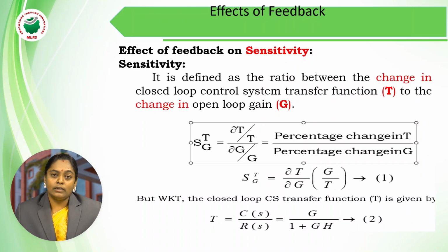The next parameter is sensitivity. Before going for the derivation of sensitivity, we must first know what is meant by sensitivity. The name itself indicates variation of output with respect to small changes in the input. It is the ratio of the change in the closed loop control system transfer function T to the change in the open loop gain.